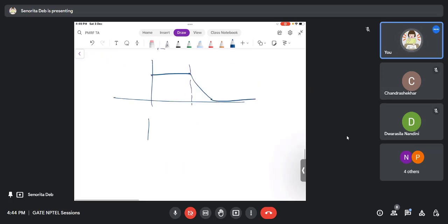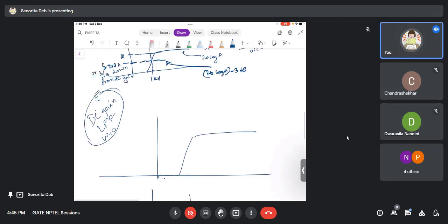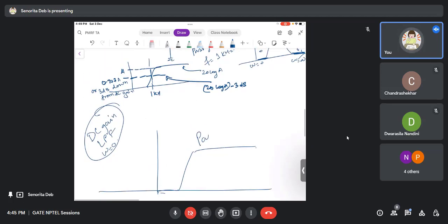If you remember, we have this kind of waveform, right? For BJT, MOSFET, everything, we have this kind of waveform for amplifiers. We draw it like a band pass filter, but it is the same thing. It is kind of a low pass filter only. So here the concept of DC gain is there. But when I say pass band gain, I can apply the pass band gain term to a high pass filter as well, because it is just the gain which the filter shows when it passes the signal.